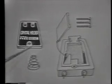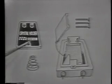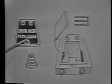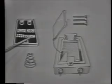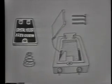The crystal holder cover usually indicates the fundamental frequency for which this particular crystal was cut. In this case, the crystal was cut to oscillate at a fundamental frequency of 430 kilocycles. Now, so far we've seen the physical characteristics of the crystals. Let's now see how the crystal reacts electrically. To do this, we'll look at the electrical equivalent of a crystal and its holder.